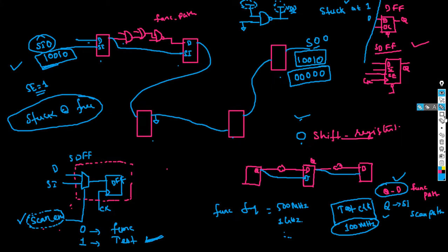Now for this testing purpose, you are adding extra circuit. If you are trying to keep more frequency, you would end up optimizing your circuit a little more on the test paths and so on. So the tool would add a lot more cells on the paths, basically buffers and inverters for taking care of transition.